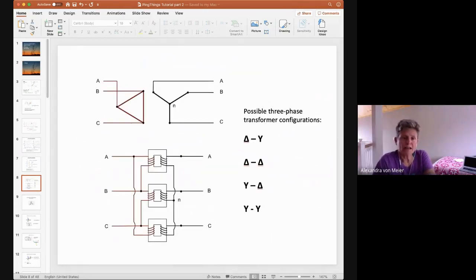So I had shown you last time that in going from a three-phase system to an actual plug, you always have to pick two places to connect to. And there's fundamentally two strategies for doing that. One is to connect between two phases, AB, BC, CA, or connect between any one phase and a neutral point. And the neutral, for our purposes, is basically the same as ground. Now, in practice, engineers worry a little bit about how close to ground the neutral really is, because during a fault, some bad stuff can happen.